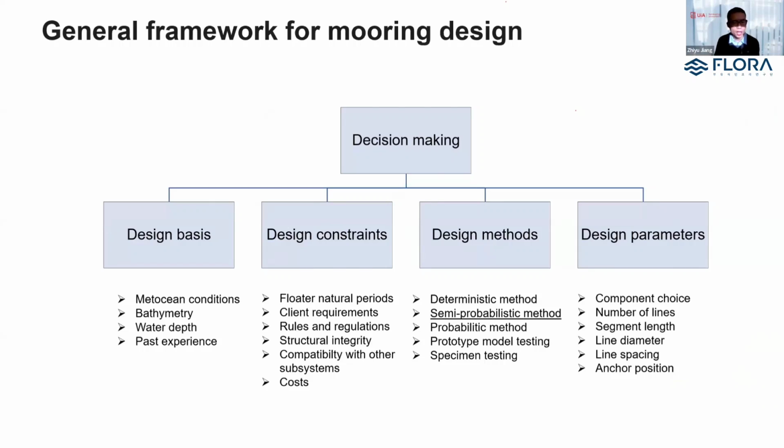The general framework for mooring design is something that I want to present. First, we need to look at the design basis. What will be the starting point for our design? The metocean conditions, the extreme wind and wave conditions, the ocean bathymetry, water depths, as well as past experience. This is something that we bring along with us when we start our design.